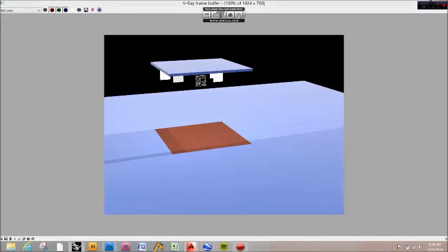So see, the white planes, they are the V-Ray material, the V-Ray material of emissive glass. They are not really creating light. They look like they're creating light. The one that's really creating light is this weird looking thing right here in the middle. That one you have to learn how to hide, and since it's within the walls, no one will ever see it. But that is what's actually making your light.